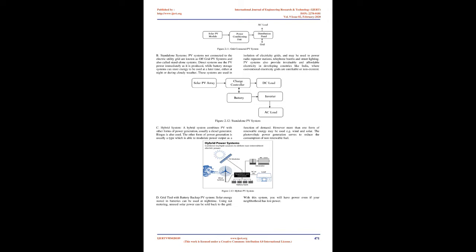2.1 Photovoltaic cells. A device that produces an electric reaction to light, producing electricity. PV cells do not use the sun's heat to produce electricity. They produce electricity directly when sunlight interacts with semiconductor materials in the PV cells. Figure 2.1, Photovoltaic cell. A typical PV cell made of crystalline silicon is 12 cm in diameter and 0.25 mm thick. In full sunlight, it generates 4 amperes of direct current at 0.5 volts, or 2 watts of electrical power.